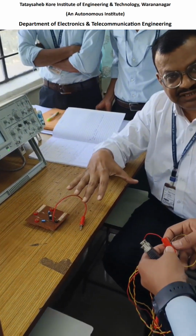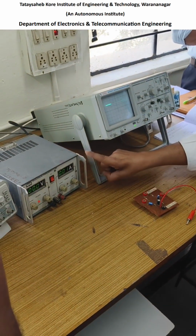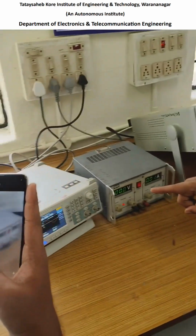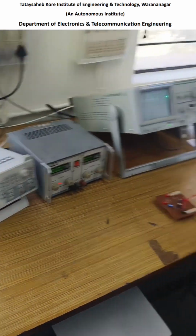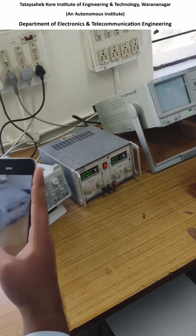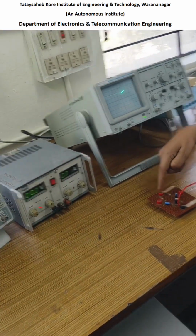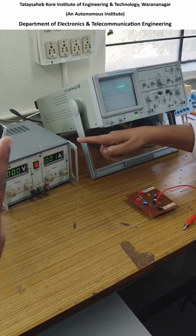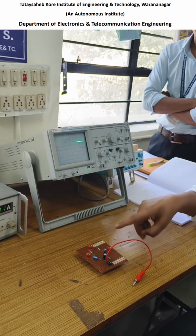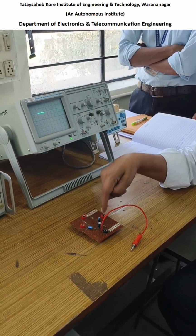Last time also you studied, you already performed the experiment. We are using this power supply as VCC. To connect the input to the circuitry, we are using the signal generator. The 20 millivolt signal you have to adjust on the signal generator, and that signal you connect here as an input to the amplifier. Here you connect the VCC from the power supply, and this terminal you connect to the CRO as an output terminal. So in the circuit, we are using these 4 connections.